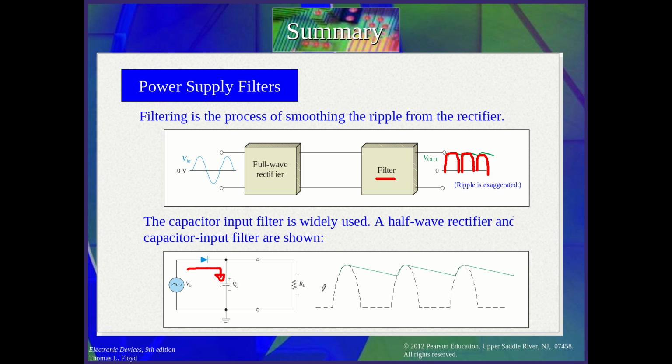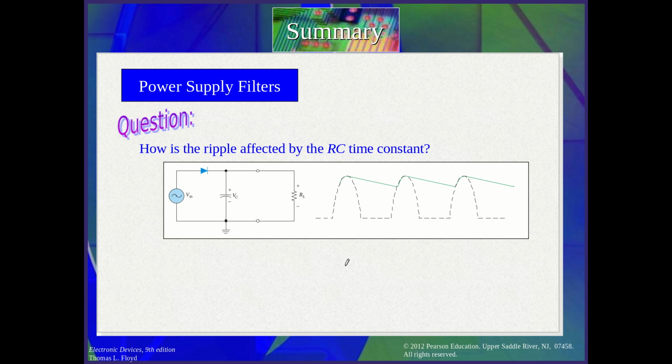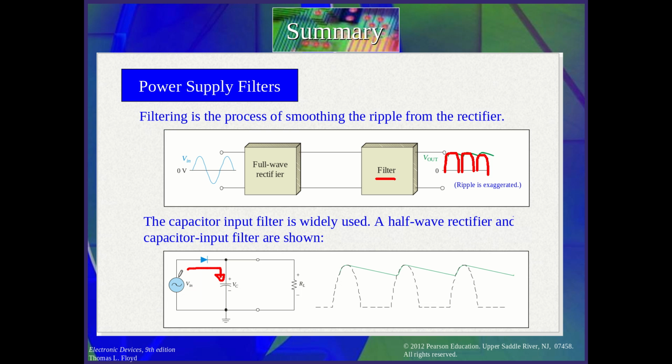So the capacitor will charge until the peak, and in the next half cycle it begins to discharge the charge it took from the first half cycle. The discharging is this line. It should reach zero, but only after a long time, and then the positive half cycle comes again. So it returns to charge, then discharge, charge, discharge. That is what makes this shape.